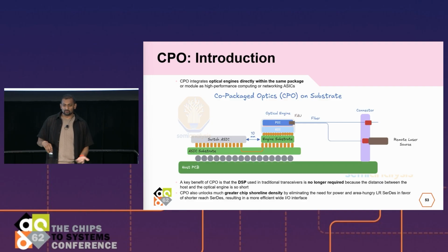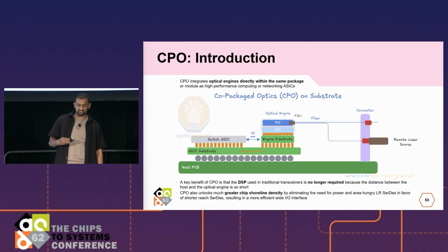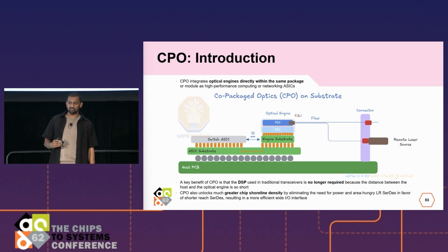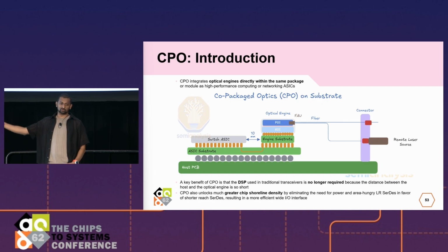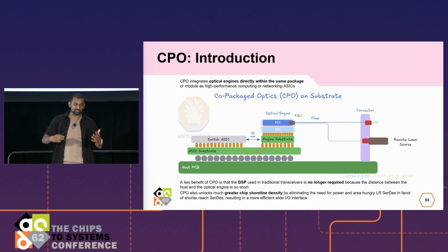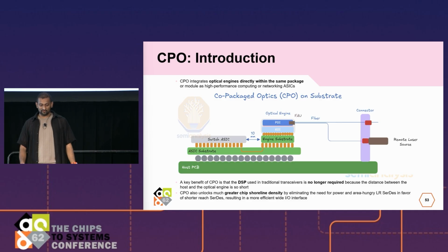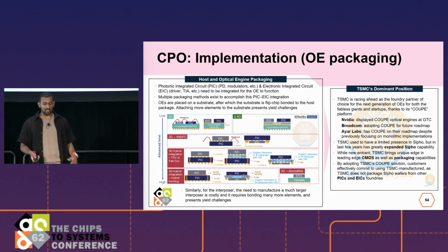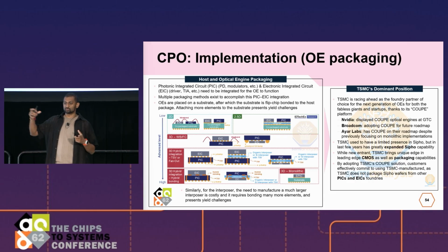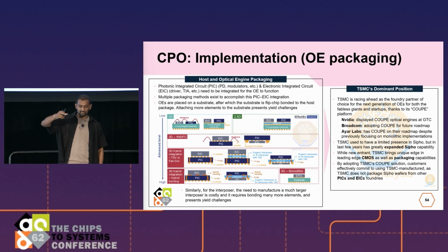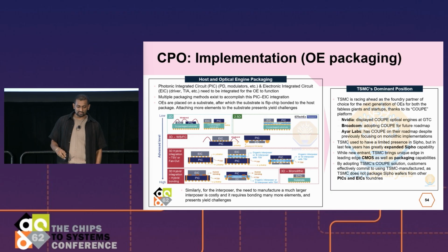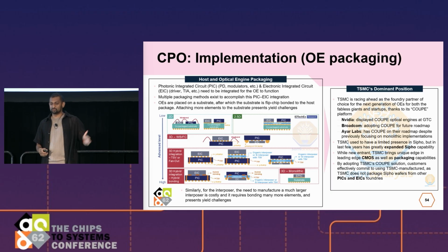And then co-packaged optics, right? Everyone's talking about co-packaged optics. NVIDIA announced it at their GTC. They're only shipping on the order of thousands of switches with it by the end of this year. But the requirements are clearly there, right? You don't have transceivers. You bring the optics onto the chip. More tight integration will be much, much faster. The challenge is that packaging this is really, really difficult. You could source the PIC, the photonic IC, and the EIC separately and put them next to each other, but that actually has a lot of issues, because getting the signal through the chip all the way to the optics has a lot of challenges.